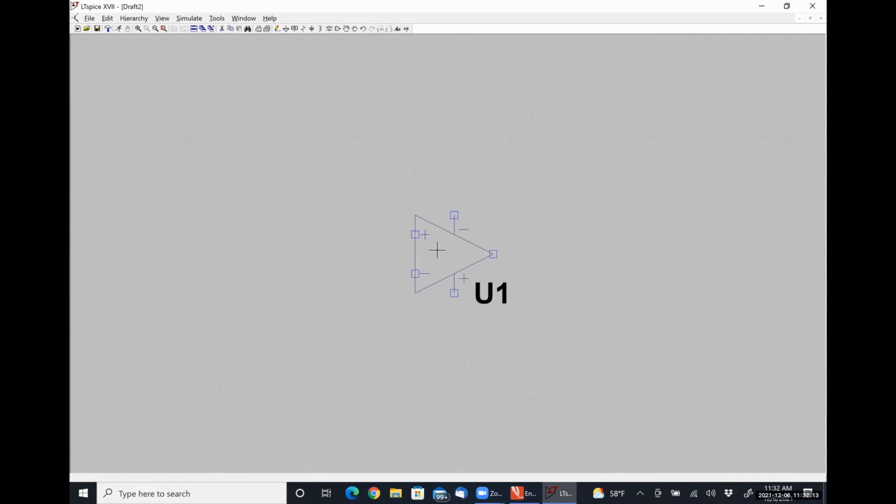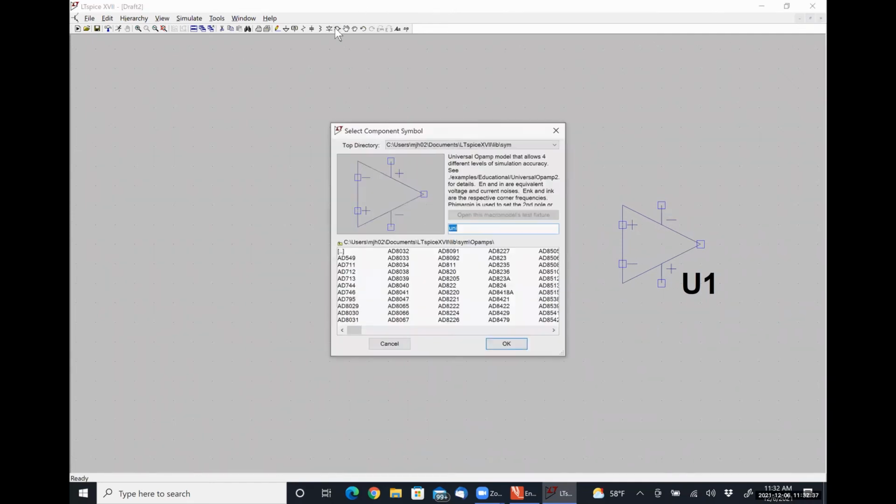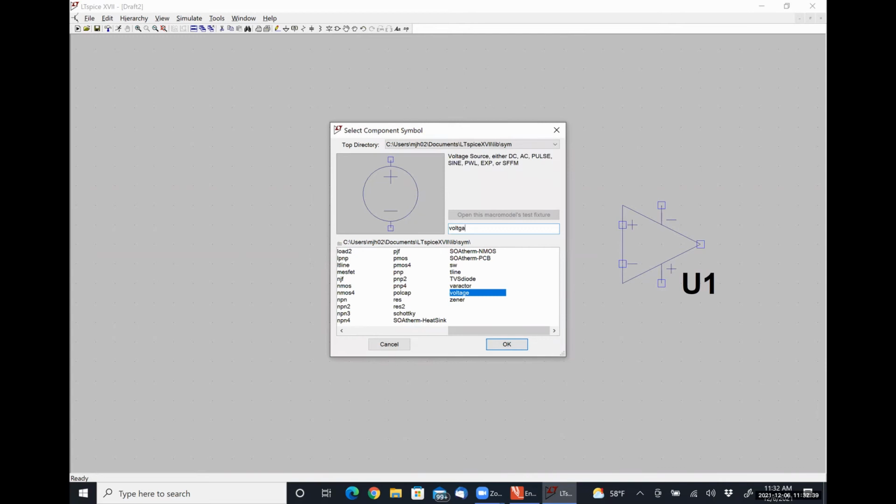All right, so I'm going to have 4 voltages in this circuit, right? VN, VREF, VCC plus, and VCC minus. To make my circuits less of a hot mess of wires all over the place, what I like to do is establish all my voltages outside the working circuit. And so I'm going to drop some voltages over here way on the left. So I press Control E to mirror it, and then I rotated it twice.